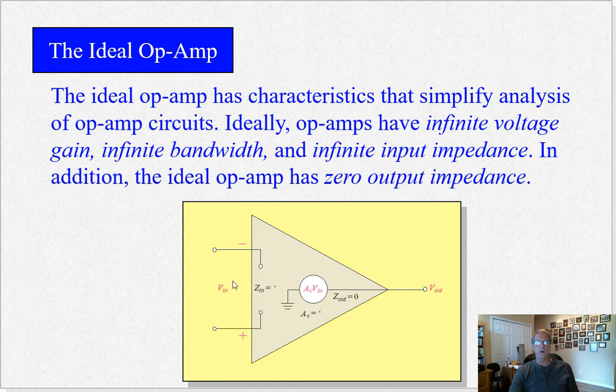Well, that's the load that's presented to the source. So if you hook a microphone up to this, I don't want the microphone to even know it's connected, right? Because if the microphone is presented with a heavy load, then the microphone output is going to be decreased, because it has to push that current into a resistor here. So you don't want any input impedance.